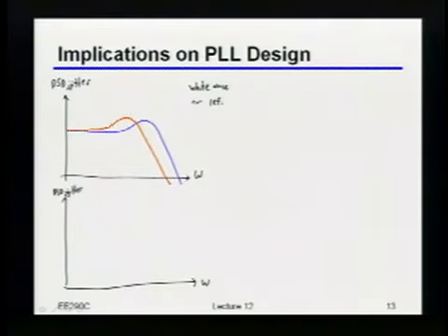Okay, now this should hopefully be obvious, but in these two cases, which one of those PLLs has more noise than the other due to the reference? First one. Yeah, the first one has more noise, right? So the blue curve has more noise just because you're integrating that white noise over a wider bandwidth. So that means that if I really care about the reference noise, or things that look like reference noise, what I want to do is make the bandwidth as low as I can, to filter all of that noise out.